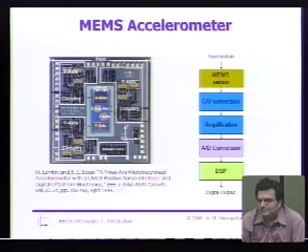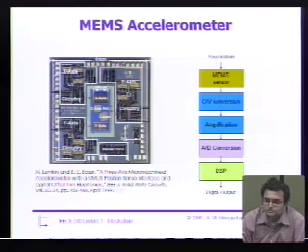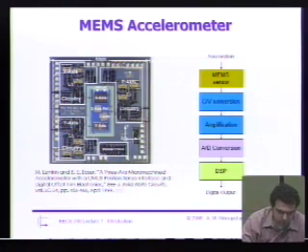The displacement of the proof mass is capacitively sensed, and then that signal, usually a current, is translated into a voltage and then digitized. That's right. And it's used in a feedback loop. They use force feedback to suppress the motion so that you get better linearity. Basically, you don't expose yourself to the Duffing nonlinearity of the spring system. Okay, let me draw a picture for what you just described.